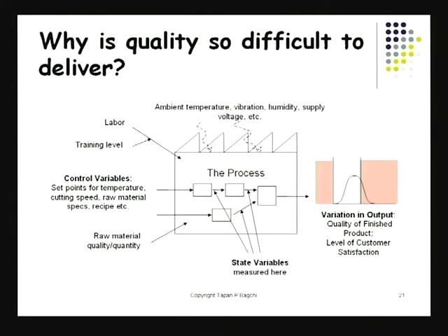If you look at a real factory, it really does pose a lot of challenge in controlling quality, because there are so many variables there, so many factors there, so many conditions there, and they are not always in your control. And things may change without any notice. Things may change, conditions may change. Rain may be there. Other disturbances may be there. Voltage may fluctuate. Raw material arrival may be different. You might have a trainee on the job, and so on and so forth. All those things that would impact quality in some way. The machine may start malfunctioning, as an example. Tools may wear out, tools may break, and so on. All these things, they will eventually have an impact on your quality.